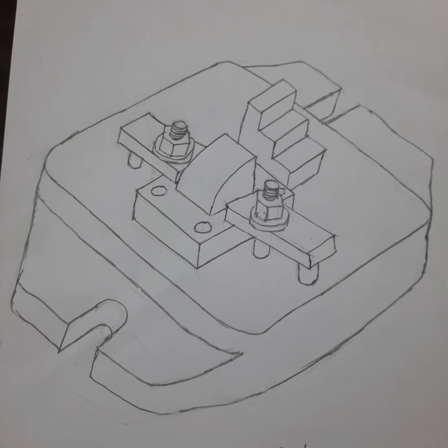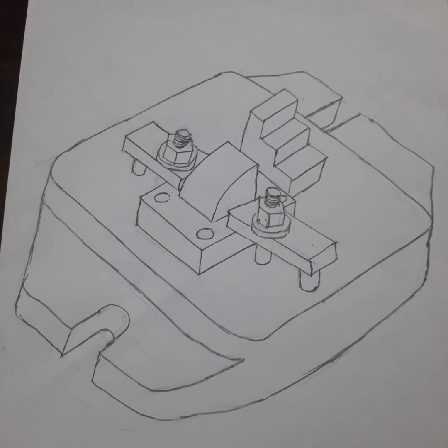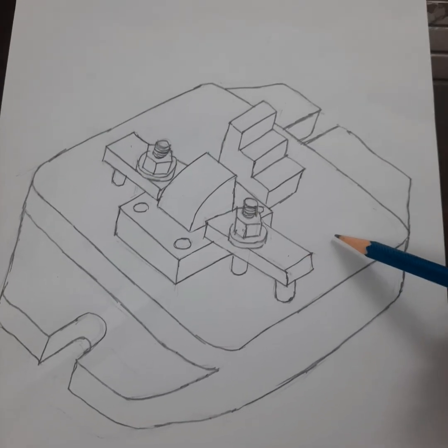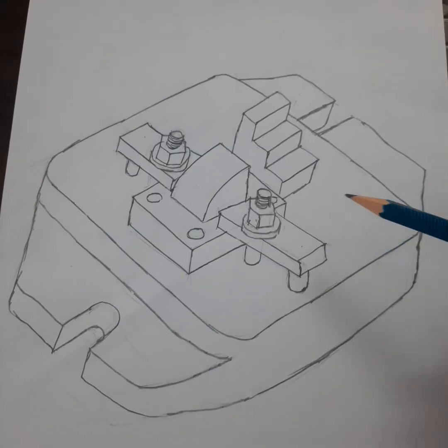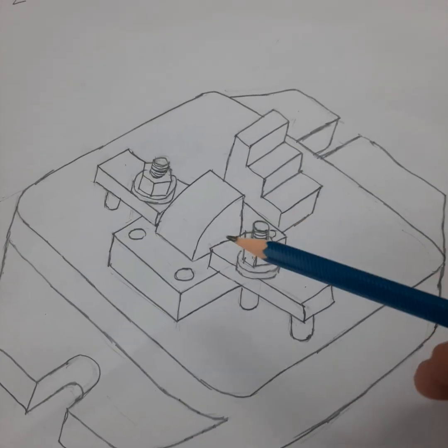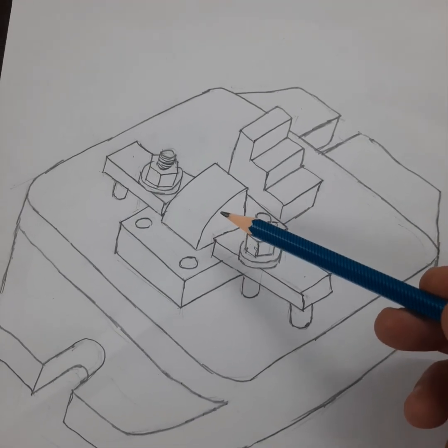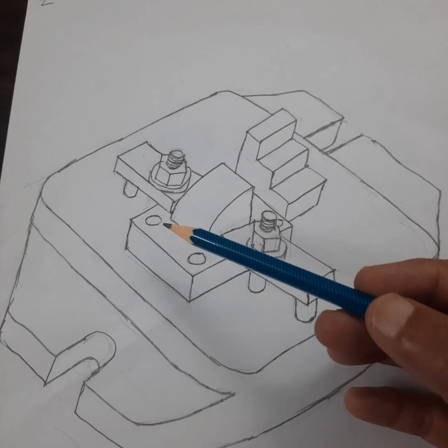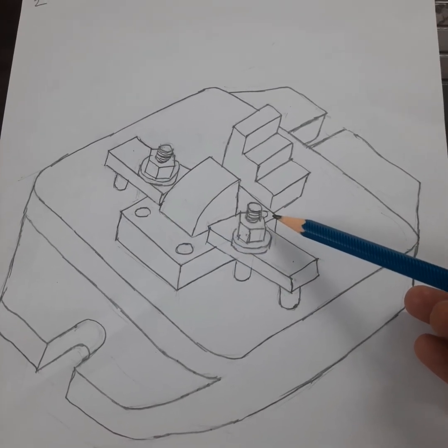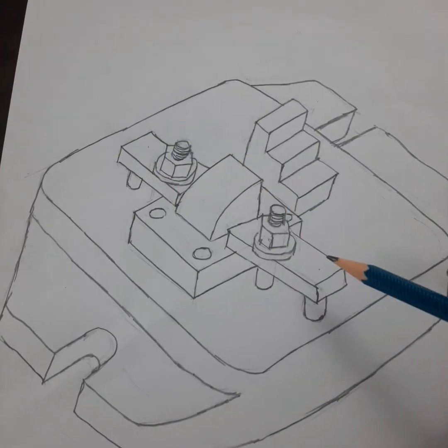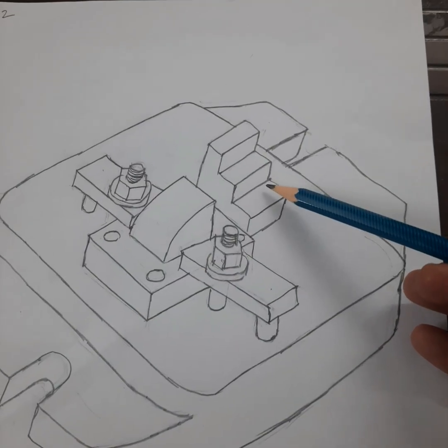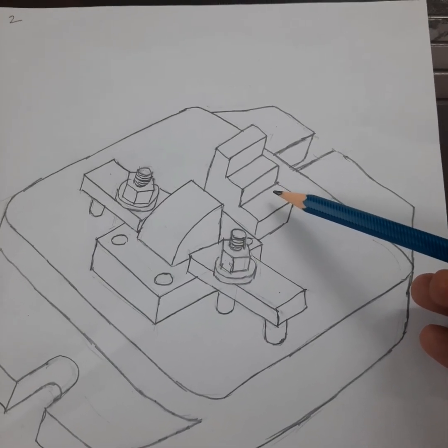So this shows the isometric view of the milling fixture. Since the fixture is going to be used on a milling machine, we call this as a milling fixture. If the fixture is used on a shaping machine, we can call this as a shaping fixture. So here the component is shown here. For locating the component, we are going to make use of one round locating pin and one diamond locating pin. And for clamping the component, we are going to make use of strap clamp, 2 numbers. And this is setting block for setting the height of the milling cutter.